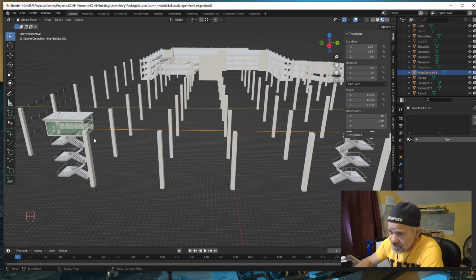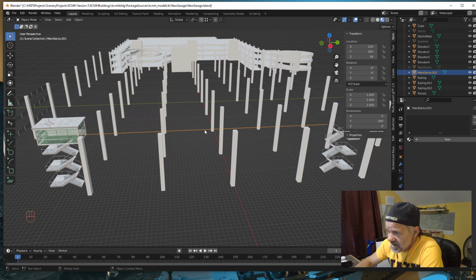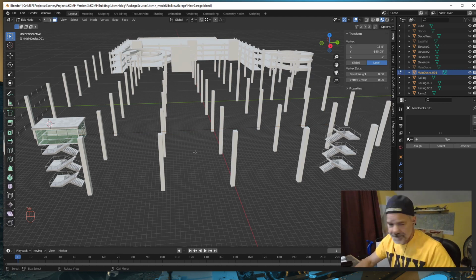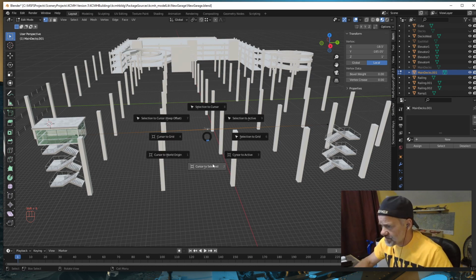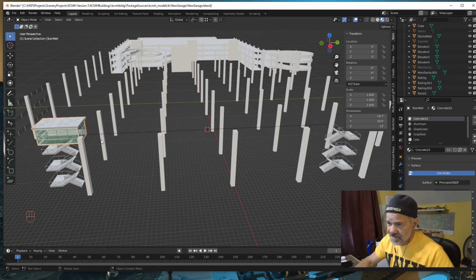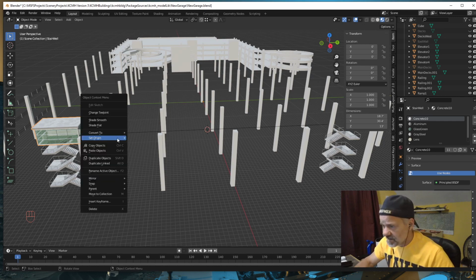So we are going to use that same edge, and we're going to move the origin of our roof canopy to the vertice that splits this line. So let's go into edit mode, tab in, turn on vertices. With that vertice selected, which it is, I'm going to Shift S, move the cursor to that location, get out of edit mode by hitting tab, select our roof, our canopy object, and right click, set origin to 3D cursor.